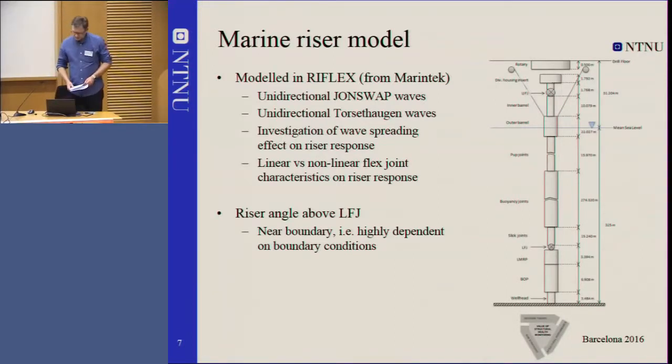So we can see that also the boundary condition on the soil has influenced the soil stiffness, because the wellhead can move if the soil is not perfectly rigid. So you have a flexible spring at the lower part of the model.